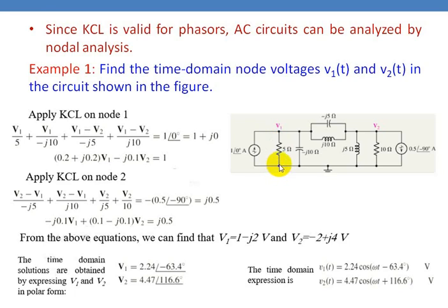So in this case, the current in this branch is outgoing, in this also it's outgoing, and the current in these two branches also outgoing, whereas this is incoming. Therefore these are all outgoing currents, so 1, 2, 3 and 4, and you can equate this current to 1 at an angle 0 degree. So therefore we can write this equation like this in terms of node voltages.